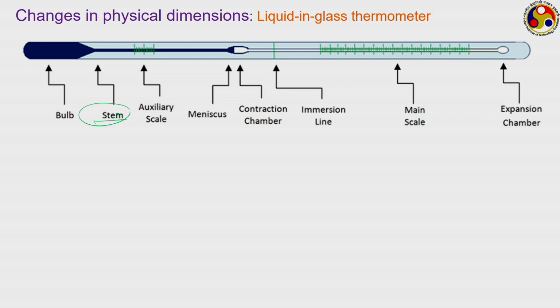And also, the void portion, like here, the dark portion refers to the liquid you are operating with, and the empty void portion of the stem does not contain any liquid at this particular moment. This should be pressurized by a certain kind of medium, so that it can avoid the column separation of the mercury column and also avoid the vaporization of the fluid inside when the temperature increases.